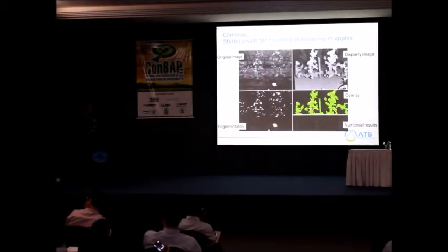So it works like this. You have the original black and white image. From that you get something which is called a disparity or depth image, which contains the distance information. You can overlay it with the black and white image to extract the white flowers, like it's done here. And from the overlay you know where the blossoms are in the first row. Because we have to look sideways, we always see the next rows on the image. And we need this 3D vision and the distance to just extract the first row.